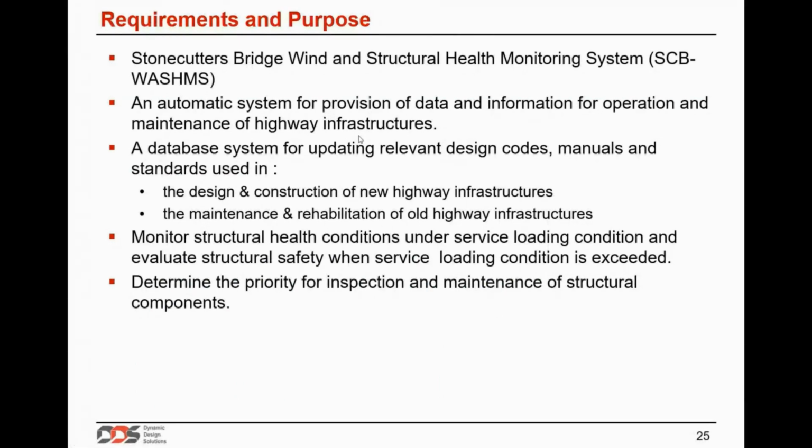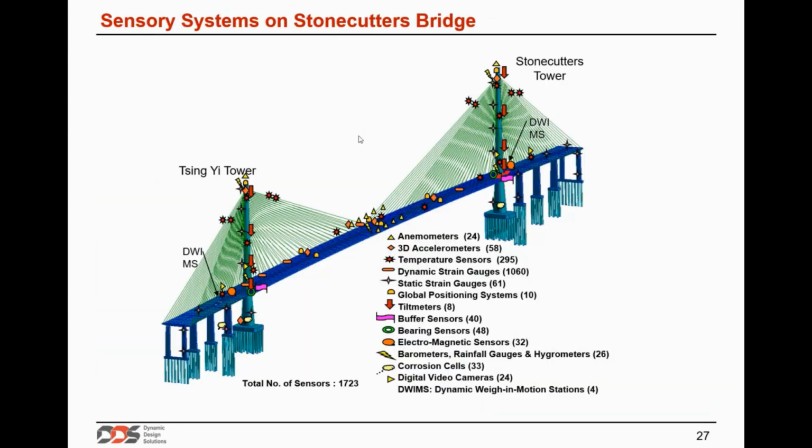information about the bridge operation and maintenance. But in the case of FEMtools, it was about the GPS receivers, so the deformation of the bridge, and the modal behavior, so using accelerometers to do operational modal analysis. There are many more systems on the bridge, like strain gauges. I think here is a list of sensor systems.